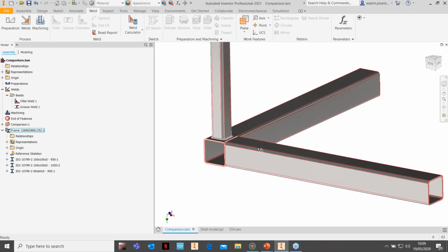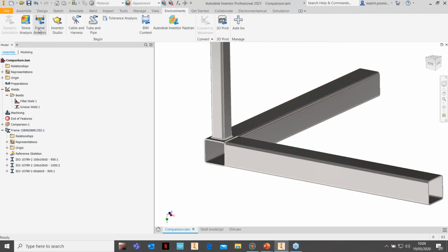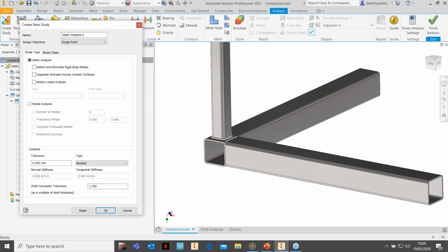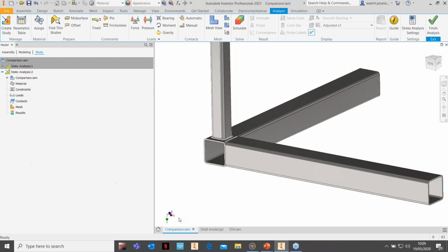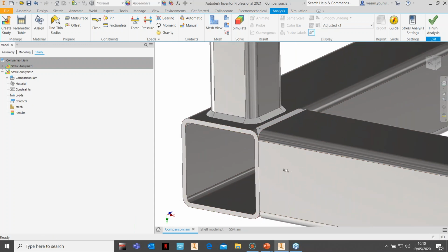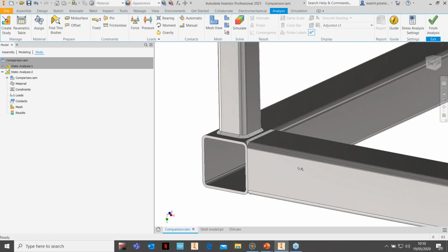And what I'm going to do here is, well, I'll tell you what, we'll use Inventor because it's the same thing as Nastran. So I'm just going to create a new study. And this process is identical in Nastran. Another best practice approach: I have seen clients using solid elements, but for something like this, you should be using surfaces as best practice dictates.